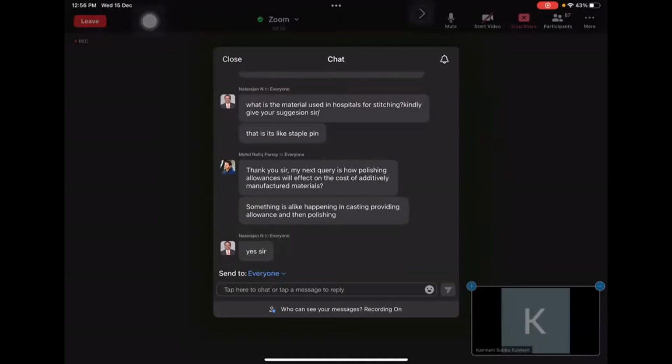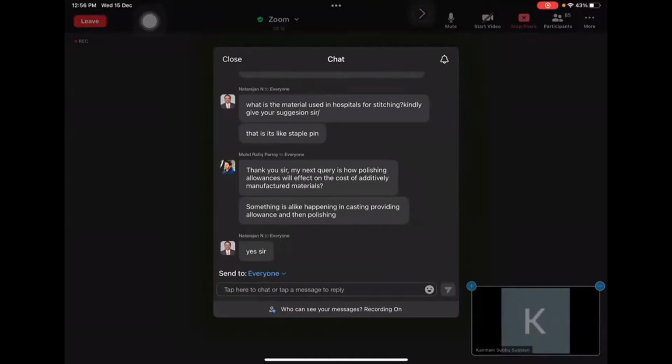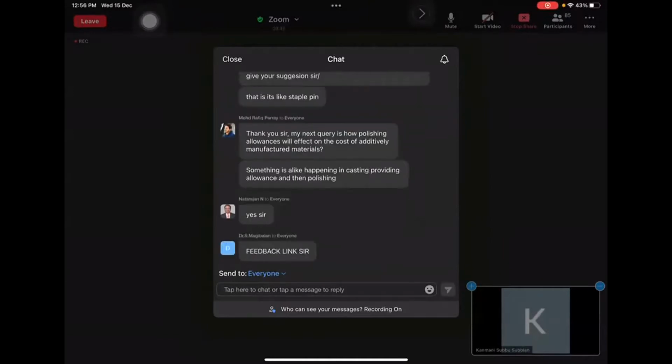Definitely it will affect, because you see how much material you're removing in each cycle. And we are anxious to reduce the amount of material to be removed. Why? Because each layer of material removed in a polishing step has some cost associated with it. Our target is to go as minimum as possible, because in conventional fabrication, you have seen that it has a multi-stage grinding process and multi-stage 5-axis machining process. So you lose a lot of material, and material is the first thing which is very expensive in implant manufacturing. So our target is to reduce.